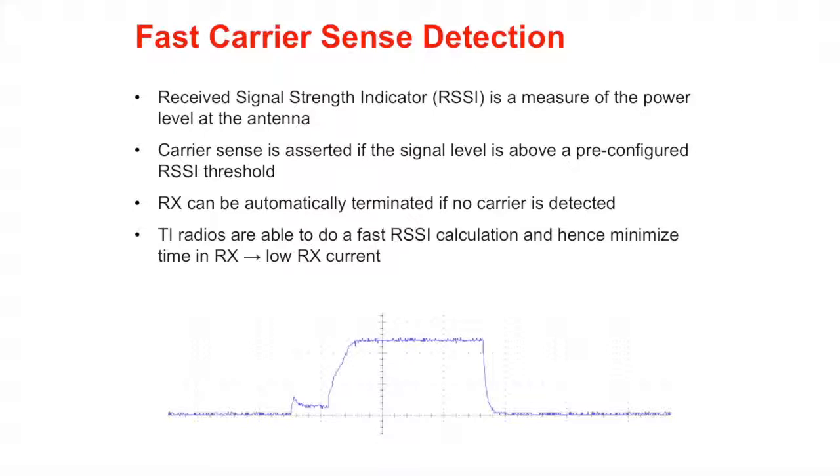The current consumption in active mode is typically much larger than the current drawn when in sleep or idle, so the time in active mode should therefore be as short as possible. When transmitting data, the time spent in transmit mode is determined merely by the packet length and data rate. The real challenge is to minimize the current consumption in receive mode, and TI's performance line radios have several built-in features designed especially with this in mind.